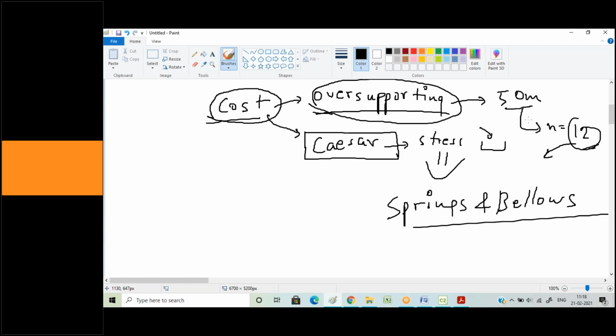Okay. If it is a smaller size, again at the same time your span might increase, because obviously even the size of the members will decrease. So say you're using an ISMB 500 for a 12-inch pipe, but if you're supporting a 4-inch pipe, the same ISMB might be 150.